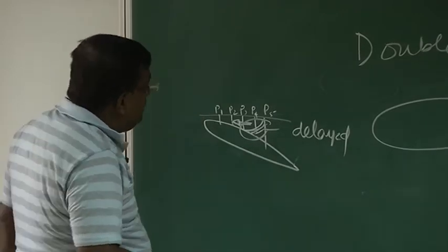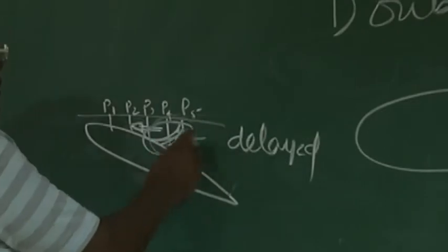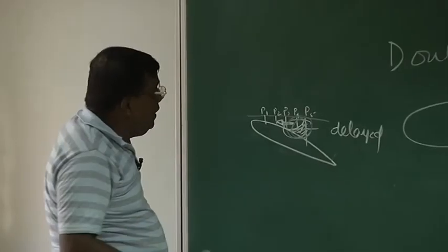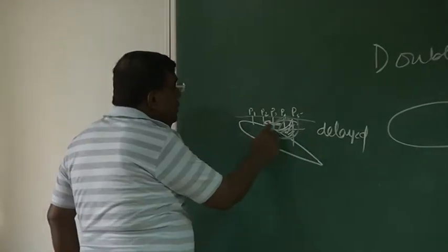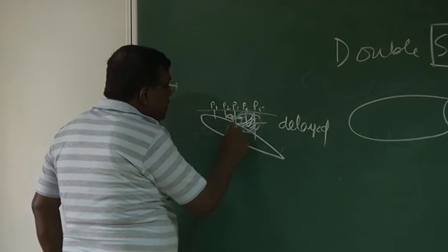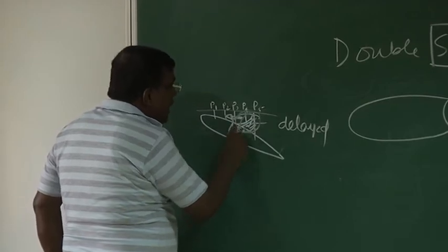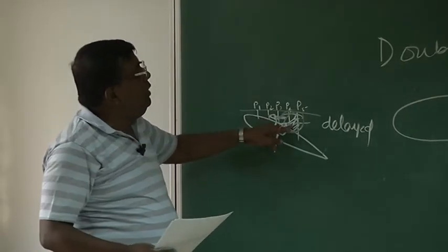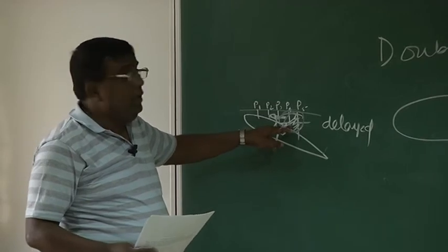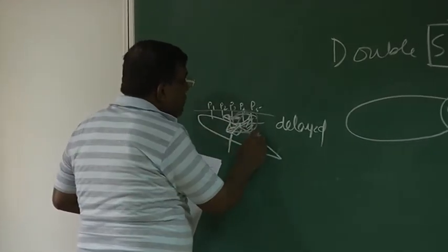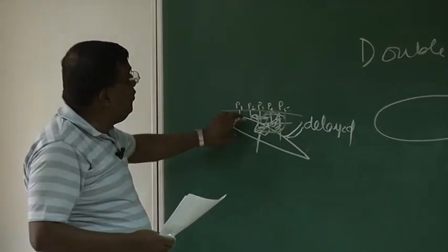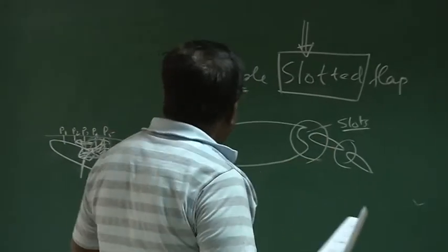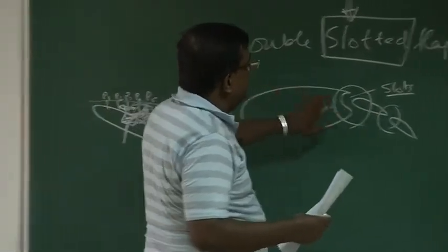By simple common sense, what does it mean to us? If this friend of ours, the boundary layer, is having a deficit of energy, I supply him energy. So what do I do? This is some fluid with high energy, I pump into this area. So that energy will revitalize this fluid particle, and this separation point from here may come here. Effectively, I can further increase this angle. Is this clear? Now, with this understanding, come back here.